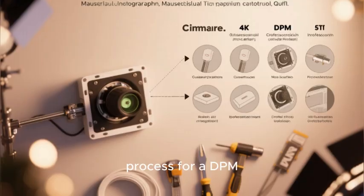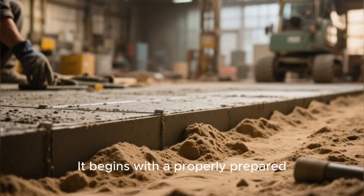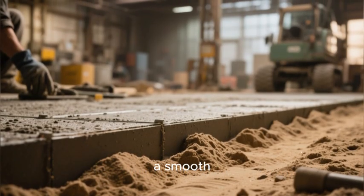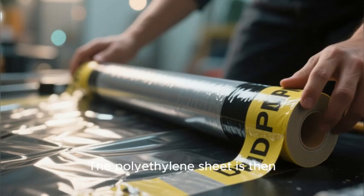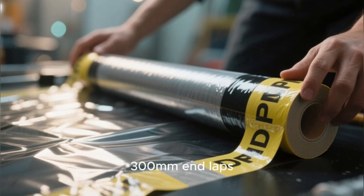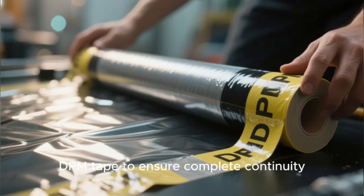The installation process for a DPM is methodical and requires precision. It begins with a properly prepared sub-base of well-compacted hardcore, followed by a blinding layer of sand to create a smooth, stable surface free of sharp protrusions. The polyethylene sheet is then rolled out with minimum 150 mm side laps and 300 mm end laps, all meticulously taped with specialized DPM tape to ensure complete continuity.